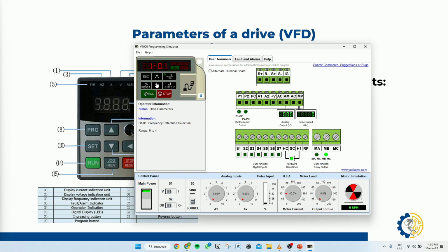So more than the electronic connections, which we're going to look into further down, which is brake resistance, the cabling for the drive, etc., all of its protections, their electrical diagrams, how everything is connected, a little bit more specifically. Aside from that, once we have everything connected, we're going to power on our drive with our switch on this side. Okay. And the first thing that we're going to do, what do you think it is? We're going to enter our motor data plate information, the one that we want to control.